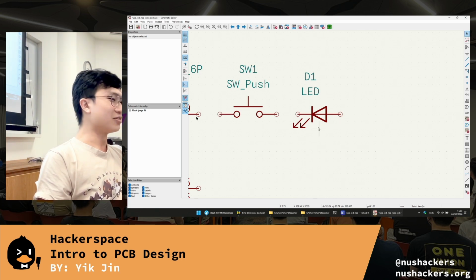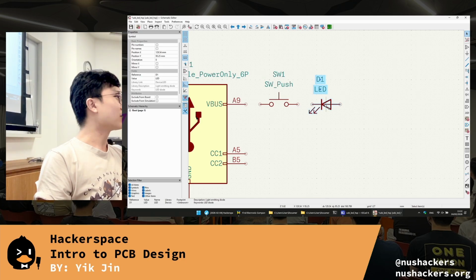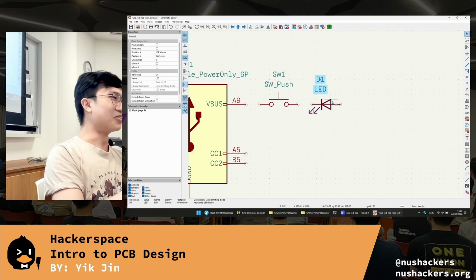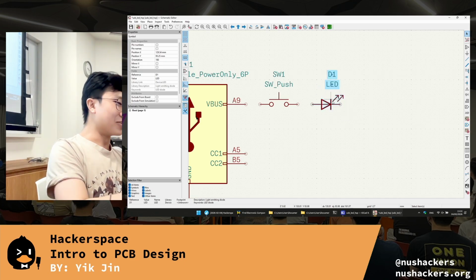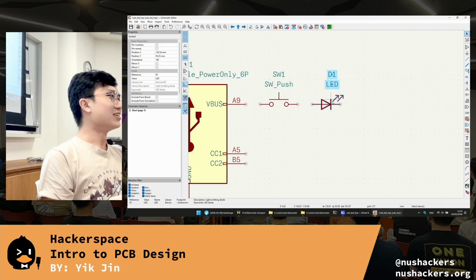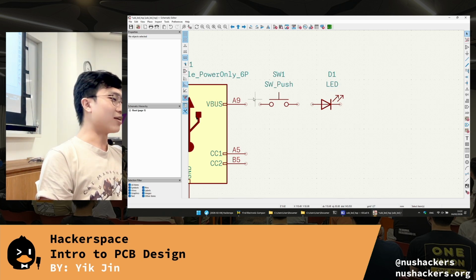So you realize our voltage, our current source, is coming from the left, which means you need to rotate this. So how do you rotate this element? You press R for rotate. You press once, you rotate 90 degrees. You press another time, you rotate another 90 degrees. So now it's pointing in the correct direction. How do you rotate it? Press R to rotate. Yes. So now it's pointing in the right direction and then I can start wiring things up.